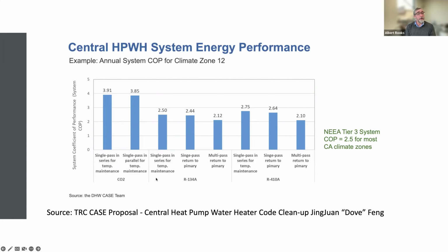You'll notice that the bottom says the refrigerant is CO2, because CO2 takes that supercritical state. It just uses less energy, works in colder ambient conditions, and always delivers higher temperature water. CO2 is the best water heating refrigerant by far. Not great at space heating. It doesn't do any cooling unless you want to freeze something. So CO2 is really your best choice for water heating.